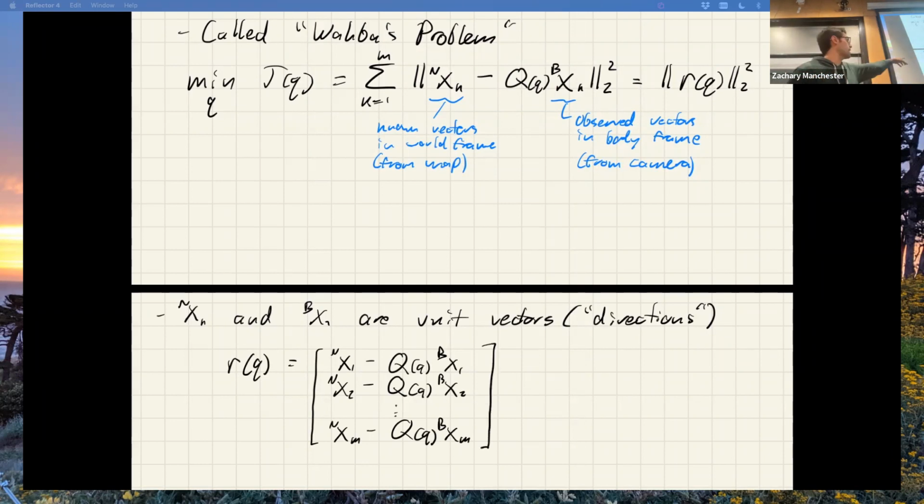And now this thing, right? This is a function of a quaternion. It spits out a big vector in R^n actually, right? I'm going to write down this guy's Jacobian. So we're going to write this grad R of Q. This thing is 3m. So I have m observations of these 3D vectors. So this guy's 3m by 3, because I'm going to take this quaternion derivative and play my trick to make it 3D. So if I write this out, it's just partial R.